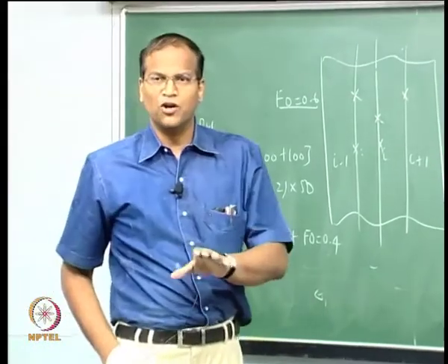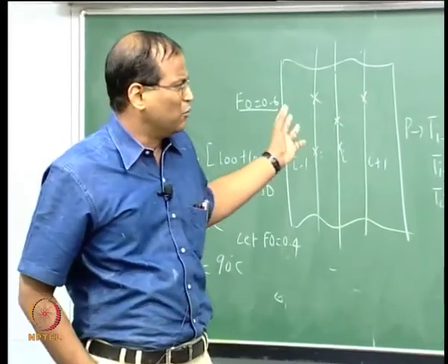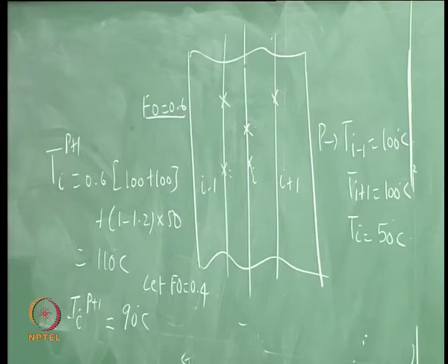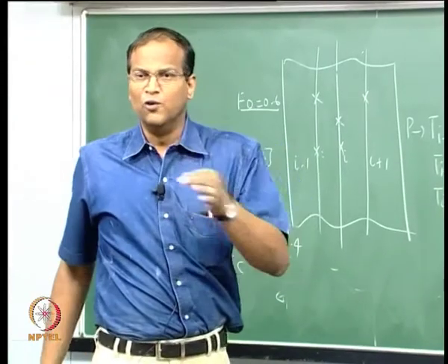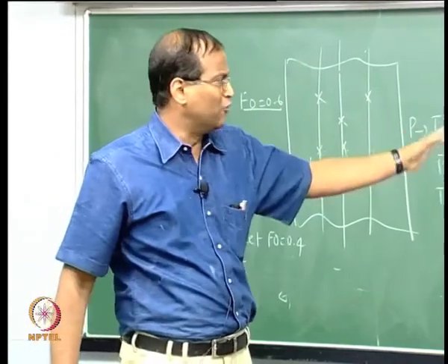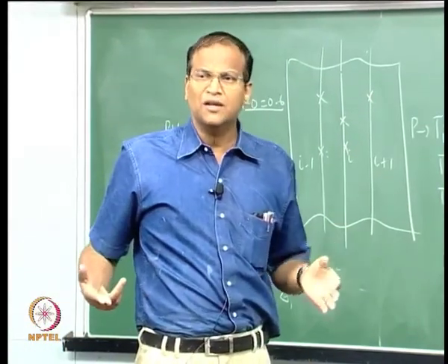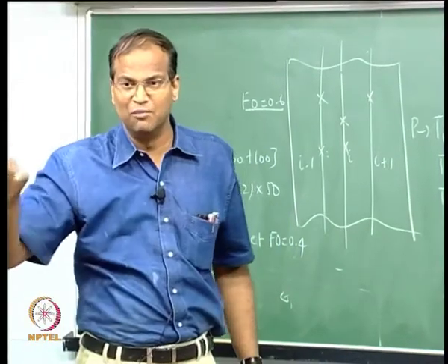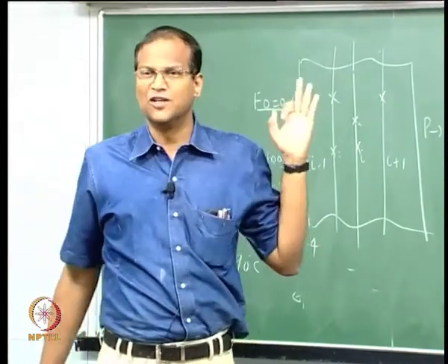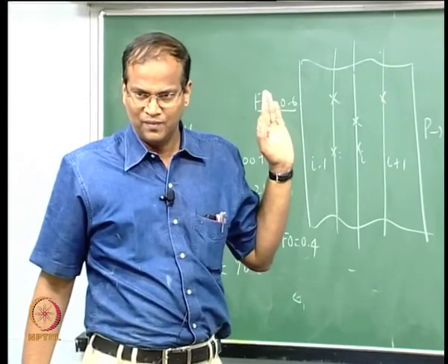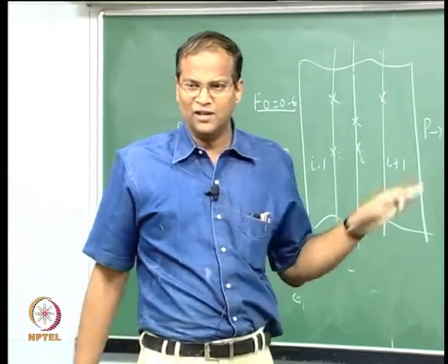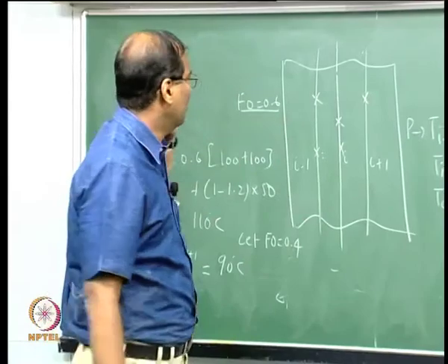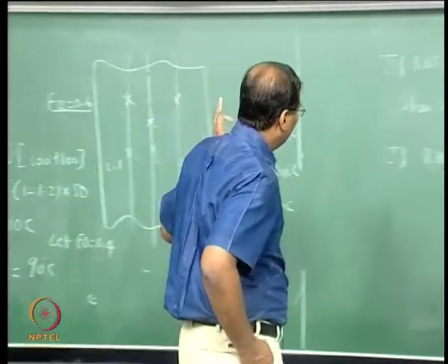So Fourier number 0.2, 0.3. So this is a quick proof of the point that Fourier number must be less than or equal to half. So therefore when you do an explicit scheme, be careful. Why do students prefer the explicit scheme? Explicit scheme is simple to solve. Implicit scheme is difficult, but it is unconditionally stable, and once you solve you get a very good solution with implicit. Okay, now you know why the cell Fourier number is very important for transient conduction, alright.